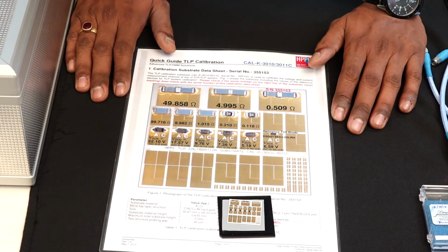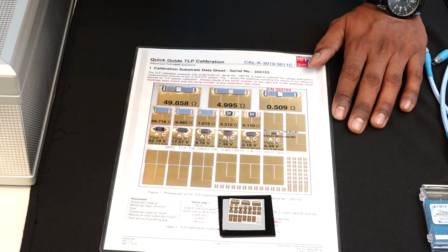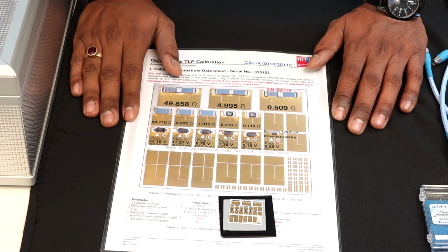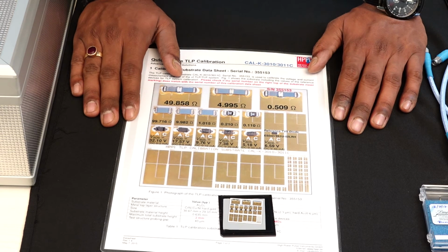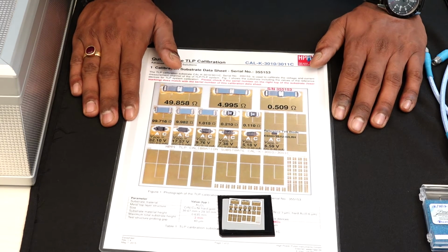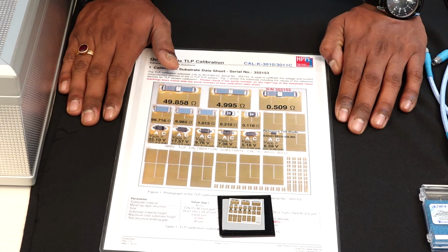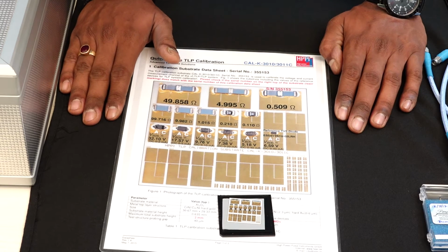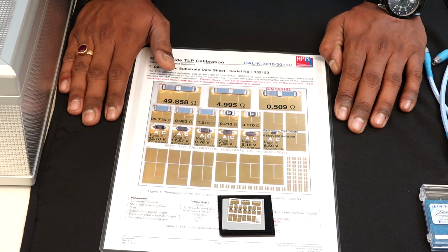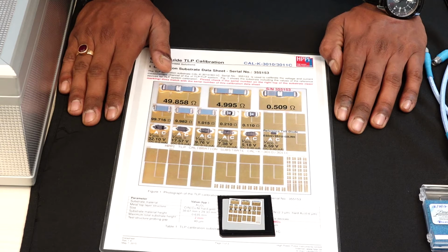The second calibration step involves a voltage channel calibration. In your whole TLP setup, I was showing you 2 different sets of lines, right? One was coming from the TLP generator to the device under test, and the other line was going from your device under test to the oscilloscope. These 2 lines also involve a lot of wires. These wires, or the components involved in them, might also have a lot of impedances, and that's why it's important to calibrate the 2 lines as well.